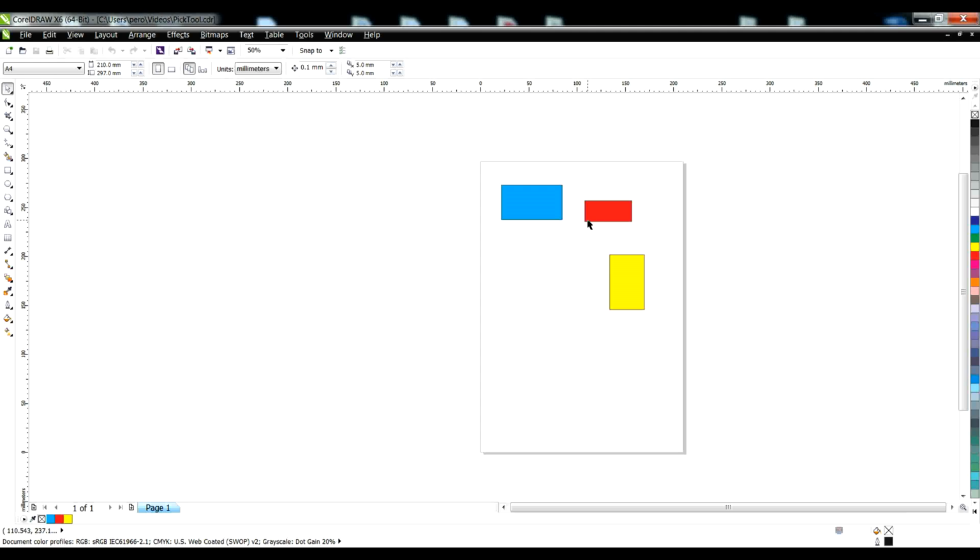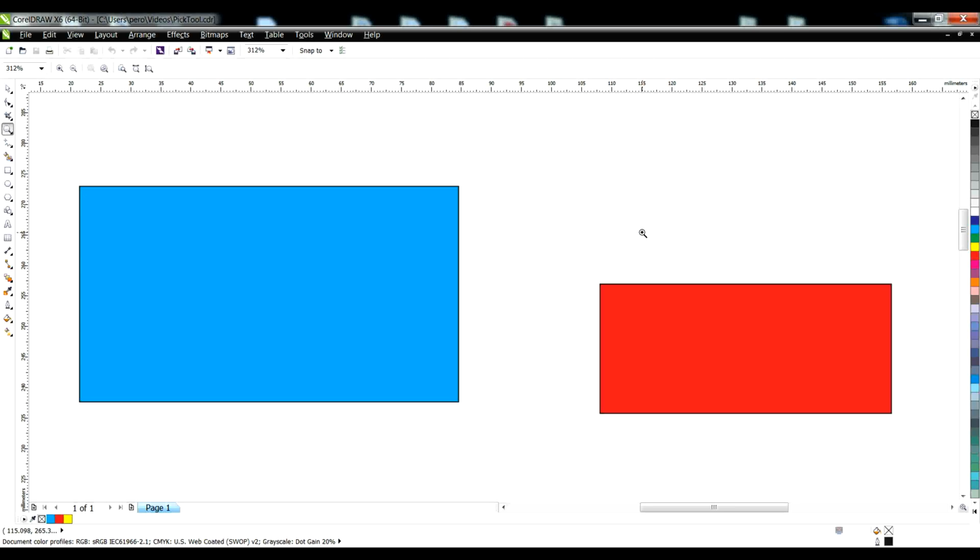The other way for zooming is by using the zoom command, the zoom tool. We are clicking on this black triangle, and we are choosing the zoom tool. Now you can see the cursor has a plus sign, and we are zooming by clicking and holding our left mouse key in this corner, and dragging with the mouse to the opposite corner. As you can see, we have a rectangle made of dots. If we let go of our left mouse key, we will zoom the objects which were inside of that rectangle made of dots.